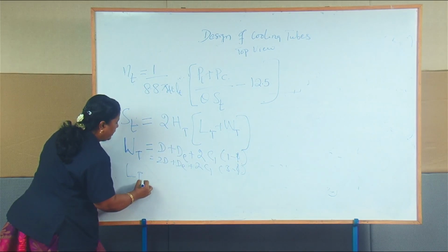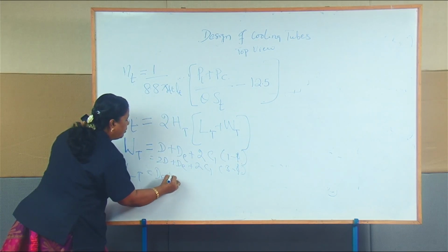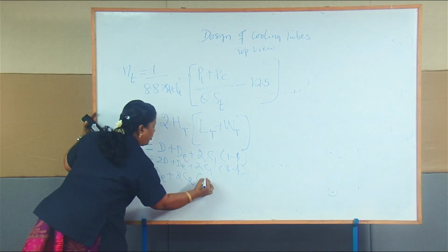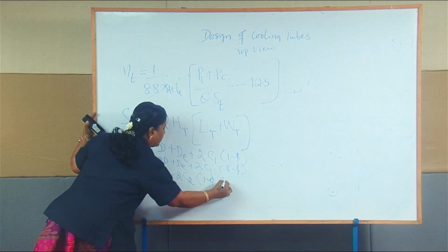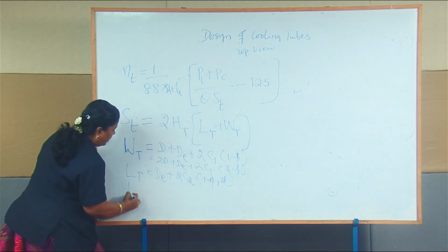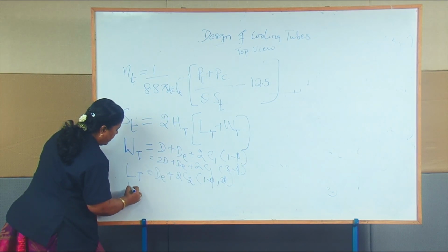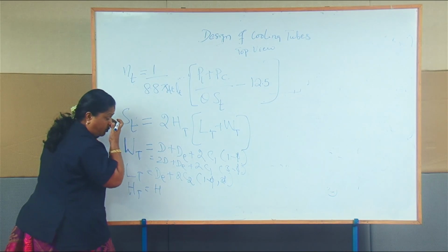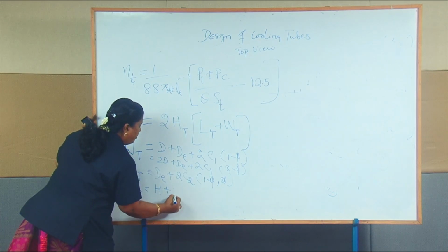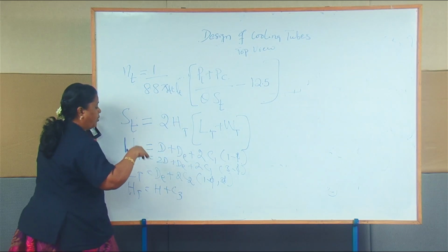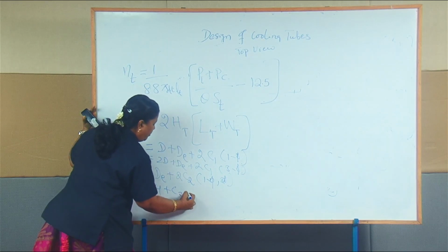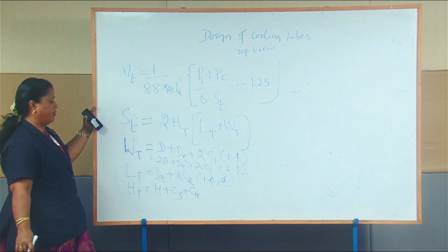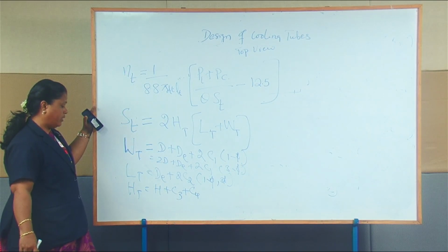The length of the tank is DE plus 2C2 for both single phase and three phase. Similarly, the height of the tank is H, the height of the transformer frame, plus C3, the clearance from the bottom to the transformer frame, plus C4, the clearance between the top of the transformer frame and the top of the tank.